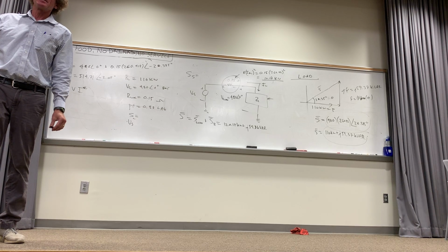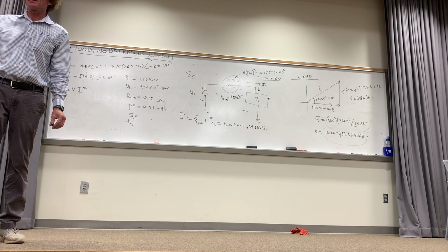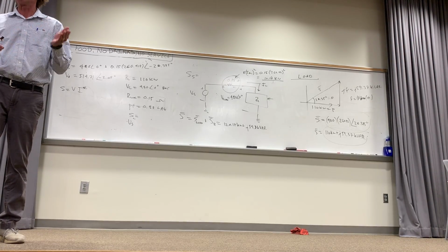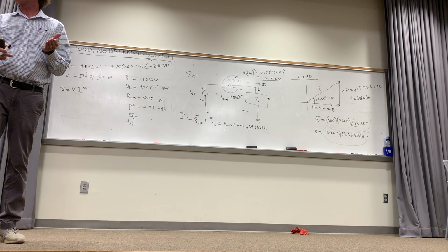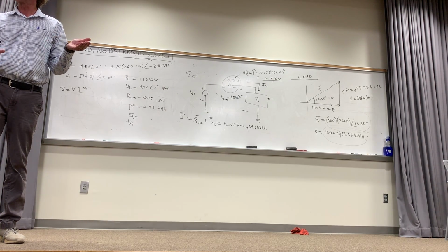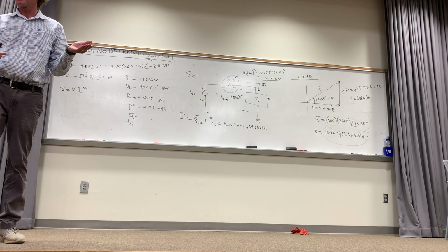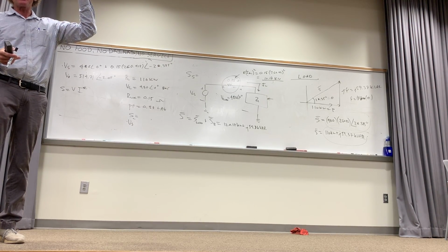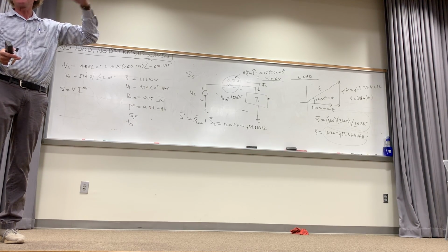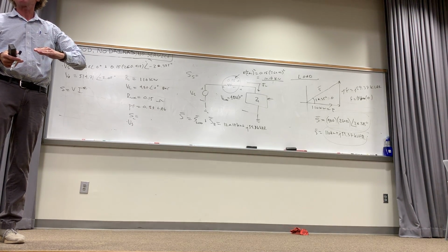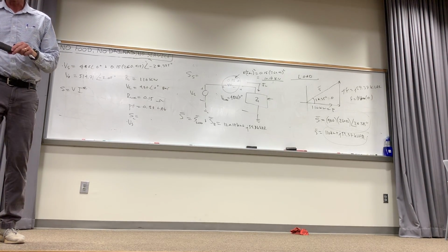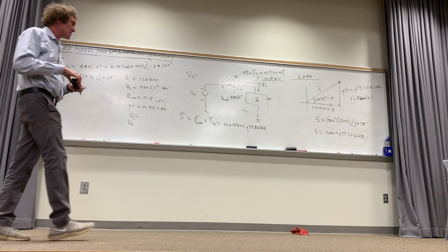Did somebody else have a question? If you look at the problems I gave you, this was the way they did it. They always got the current first, didn't they? You need the current, and you have to get the right angle with the current. After that, the problems fall apart, usually. How many understand this? I gave you a bunch of problems, and they're all basically cookie cutter problems. Same type. There's not a lot of variation. You're just juggling numbers, aren't you, class? Remember that complex power is always V times I conjugate, and it's RMS stuff.